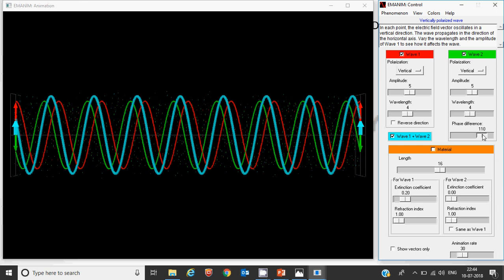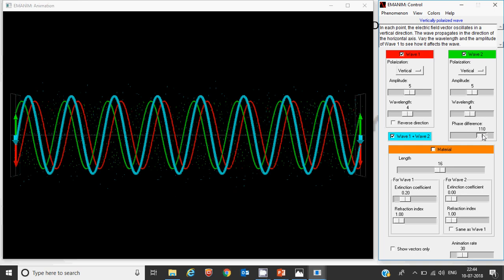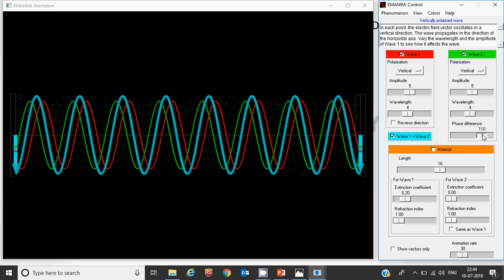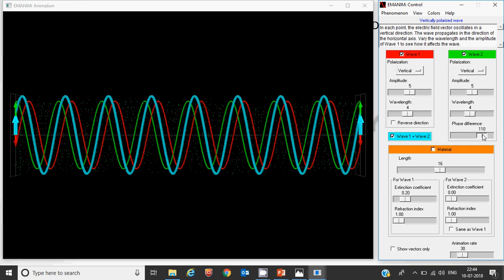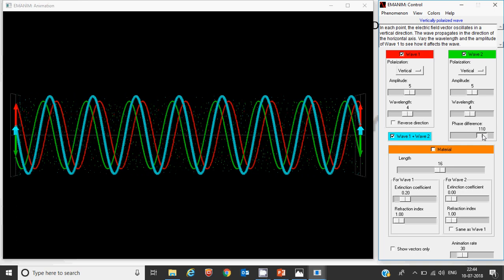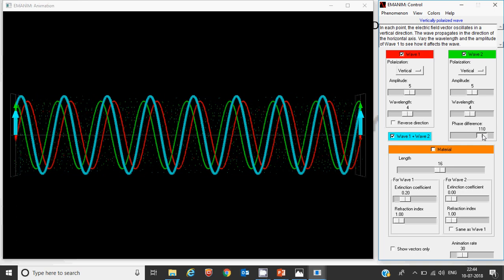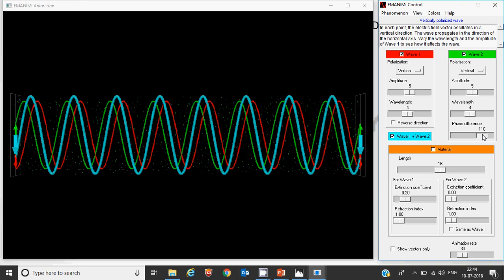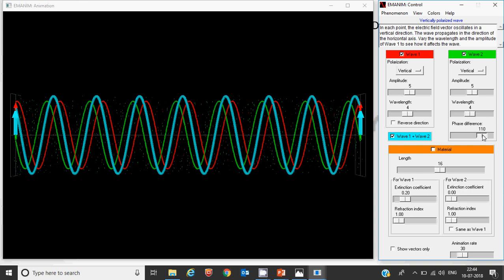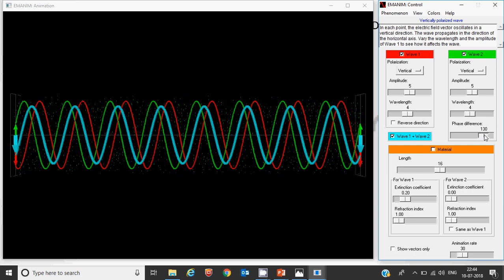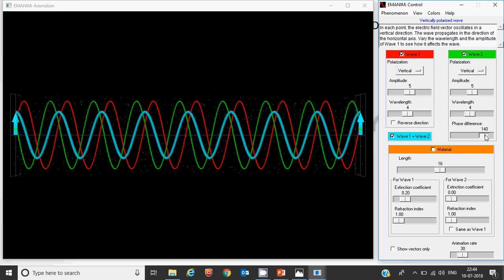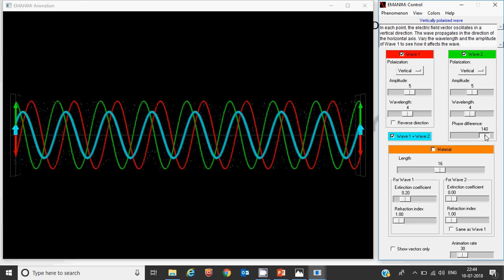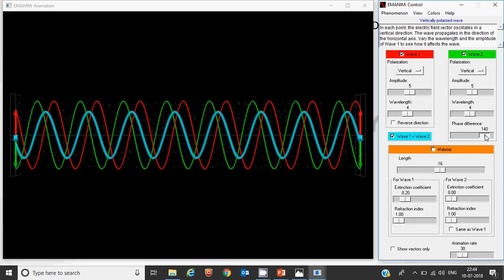So from 0 to 120 of phase difference, if two waves reach the receiver, it has a positive impact, or constructive multipath. They are called constructive multipath or up fade, and they result in a constructive amplitude. But if the phase difference of the received waves is more than 120 degrees, then it results in a down fade, or destructive multipath, like I showed here.